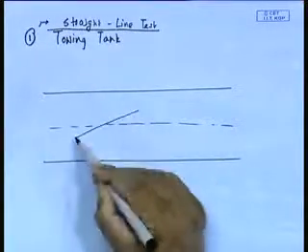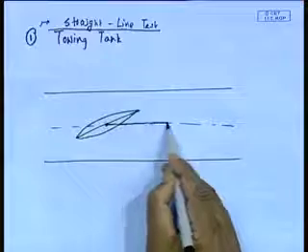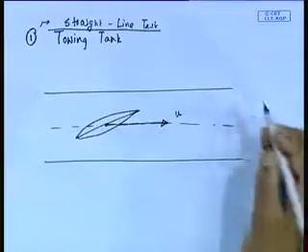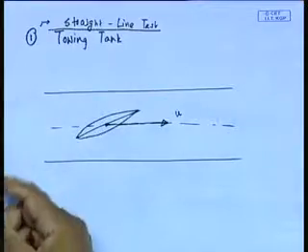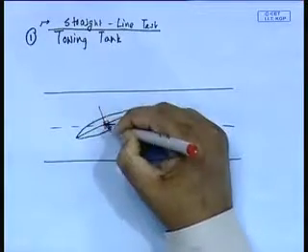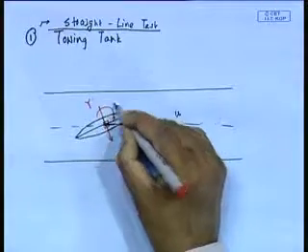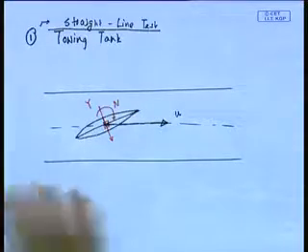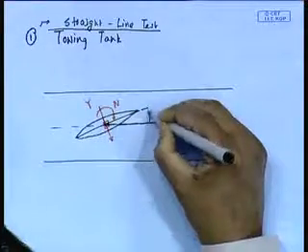All I do is keep the model inclined and tow it there at u equal to u1, and measure with a dynamometer whatever Y and whatever N. What we are doing is with an angle of attack, say. Now, here this angle of attack is taken from here.